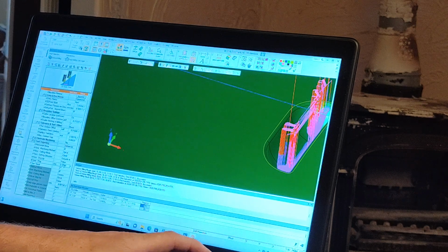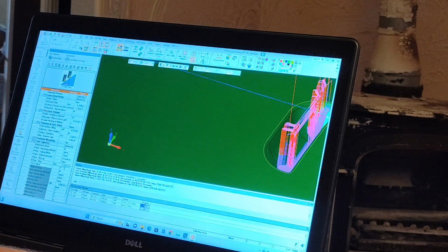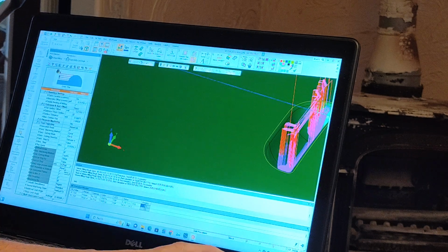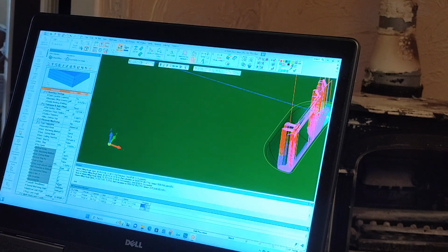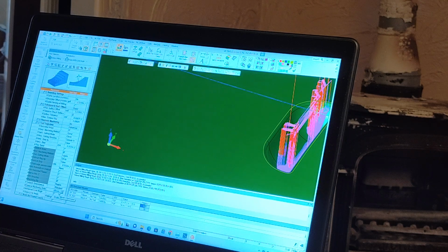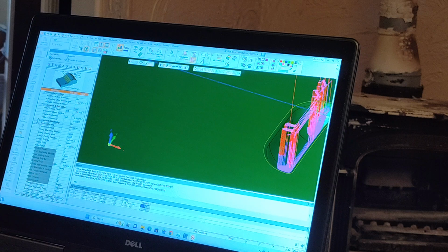So the horizontal step will be 1 side step. And a 1/1000 down step. When I'm using surface mode by limit angle, I normally do the mixed optimized. It wouldn't have much impact in this example, but it's the one I prefer. And then the slope limit angle we'll set to 45 degrees. That means that's the break between horizontal and vertical.